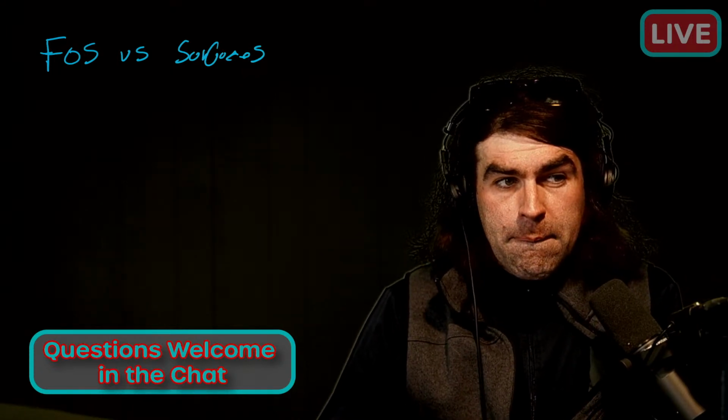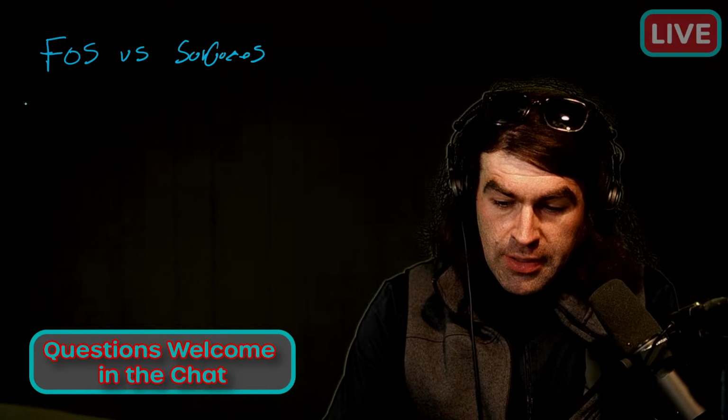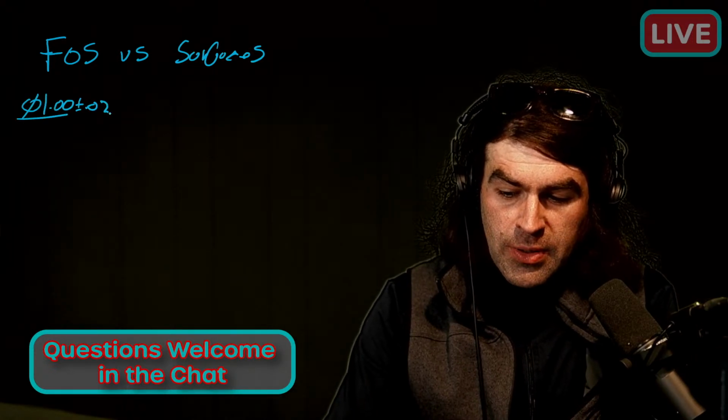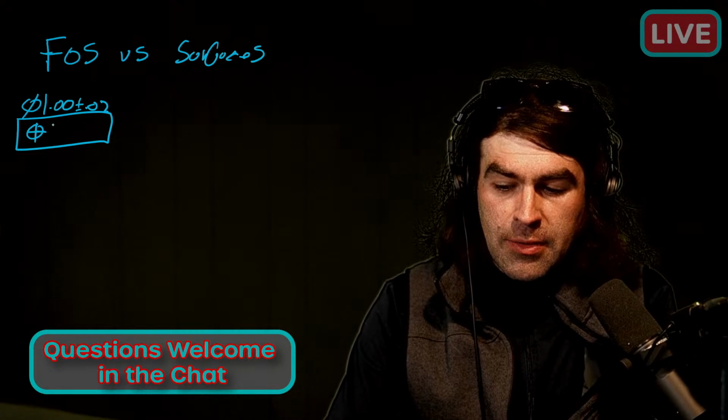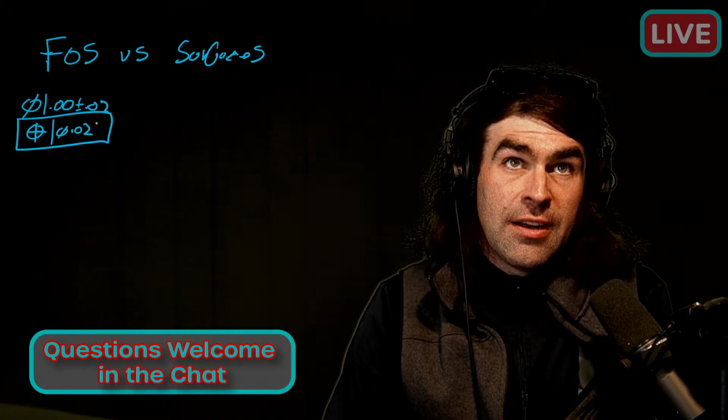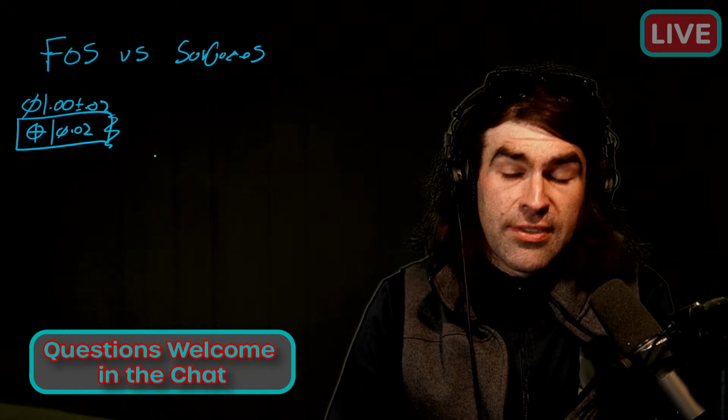So when we apply position to a diameter, the position is always going to be with the diameter, right? And that's kind of like a giveaway that it applies to a feature of size.